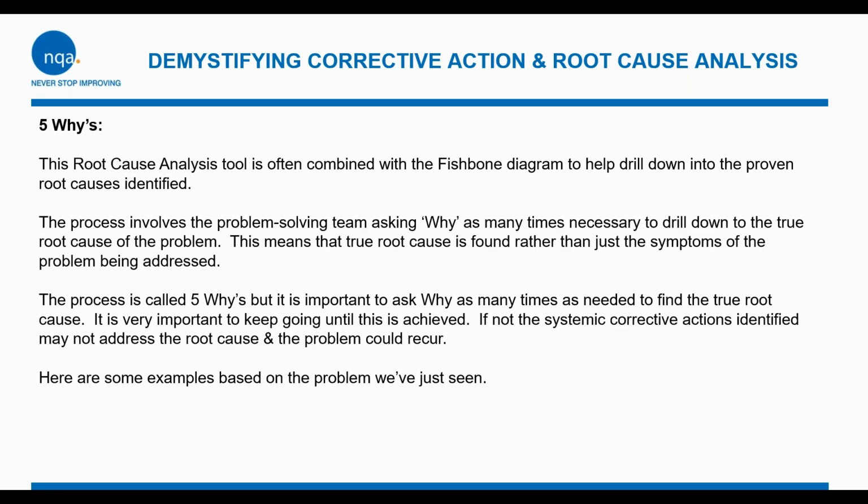Moving on to 5 whys. This root cause tool is often combined with the fishbone diagram to help drill down into the proven root cause identified. The process involves the problem-solving team asking why, not just 5 times, but as many times as necessary to drill down to the true root cause. This means that the root cause is found rather than just the symptoms of the problem being addressed.